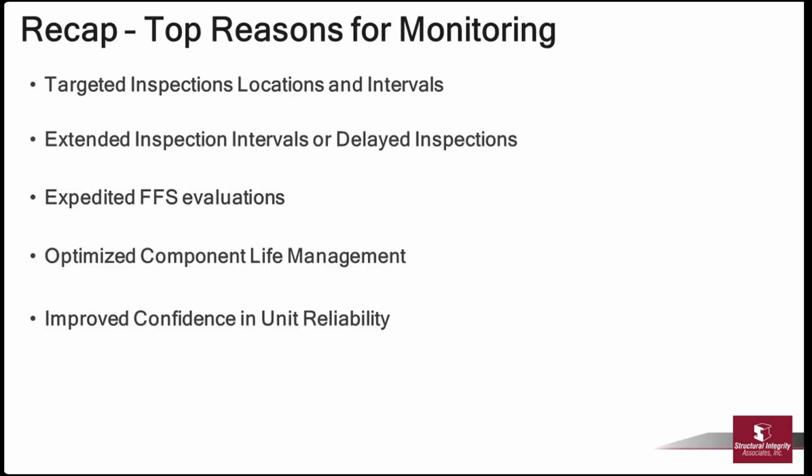We're basically just looking over time at the wall loss on those elbows, and we've identified about 28 thousandths wall loss on one of the elbows over a 3-year period.